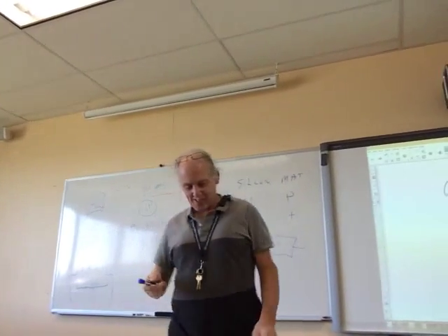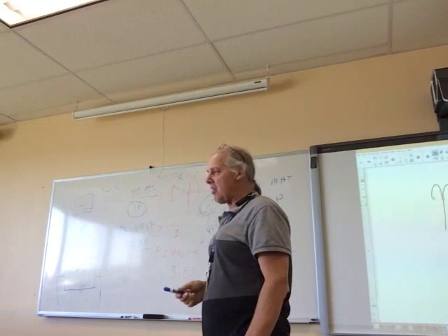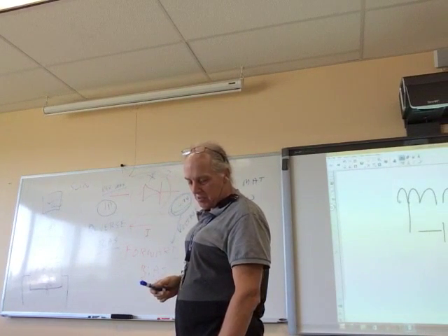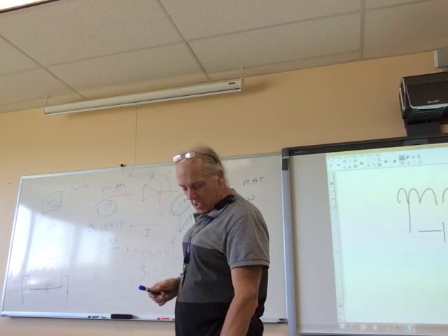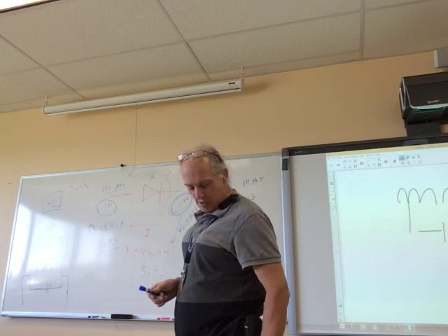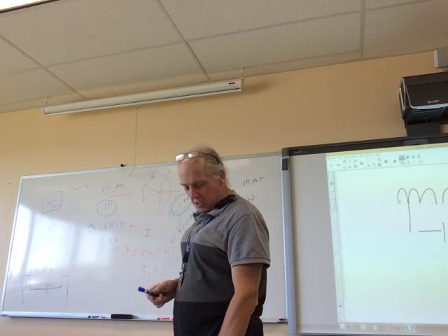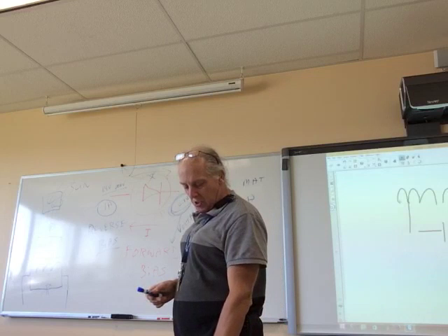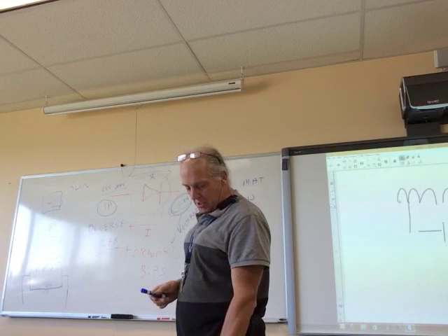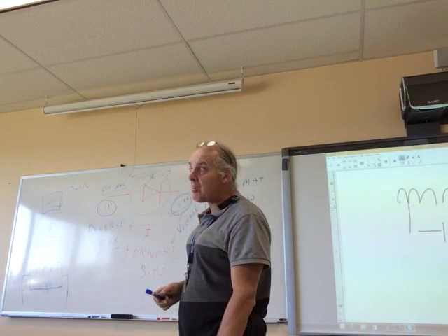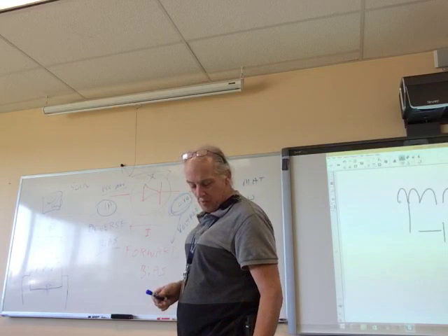Okay, so, all right, if we move through the book, you notice that's all there is on diodes on silicon and silicon junctions. Now, the next chapter actually shows the junction. Go to page 209, and you'll see the depletion layer, well, 208, you'll see the depletion layer, okay? You'll also see that they show the negative and the positive charges, the electrons and the holes, and the migration with a battery and a limit resistor. If you put a battery on it, a power supply, make sure you have a limit resistor on it, which we're going to do.